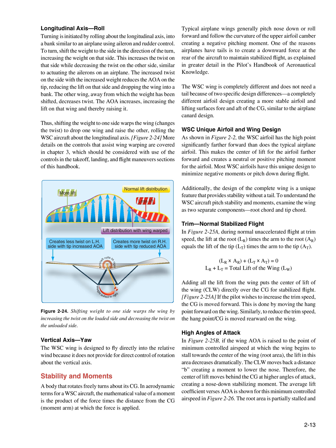The WSC airfoil has the high point significantly farther forward than does the typical airplane airfoil. This makes the center of lift for the airfoil farther forward and creates a neutral or positive pitching moment for the airfoil. Most WSC airfoils have this unique design to minimize negative moments, or pitch down, during flight. Additionally, the design of the complete wing is a unique feature that provides stability without a tail. To understand the WSC aircraft pitch stability and moments, examine the wing as two separate components, root chord and tip chord. Trim, normal stabilized flight, Figure 2.25A.